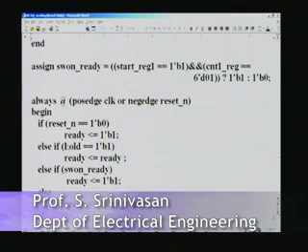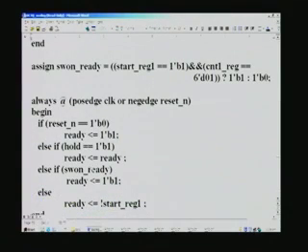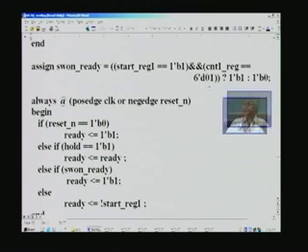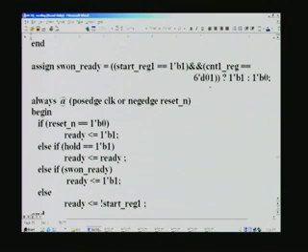We will continue with the Verilog DCTQ controller design, and we stopped last time here for the ready signal. The ready signal is turned on only if this condition is met. This condition is given here: so long as the start is asserted and we have the counter 0 1 here. This implies that we have already processed DCTQ for the previous block, and we have in fact started the current block, just at the beginning.